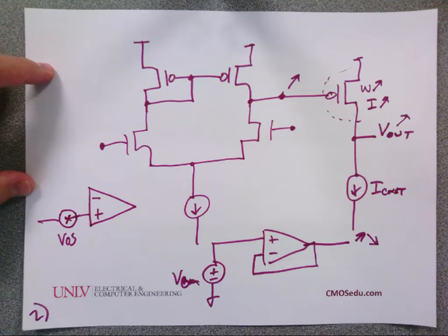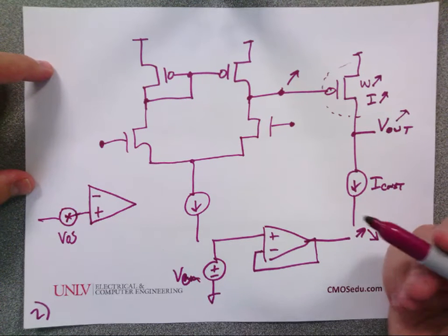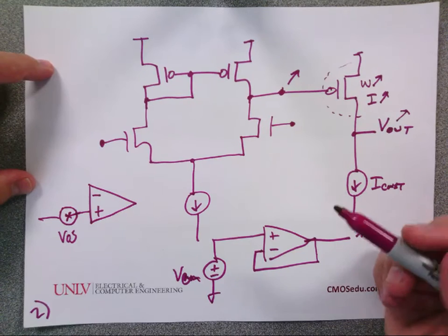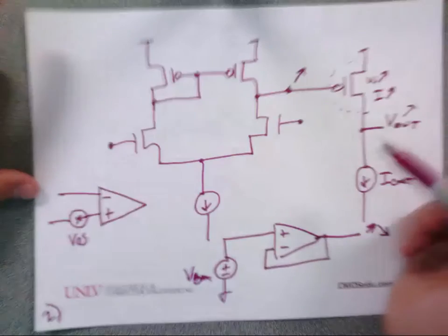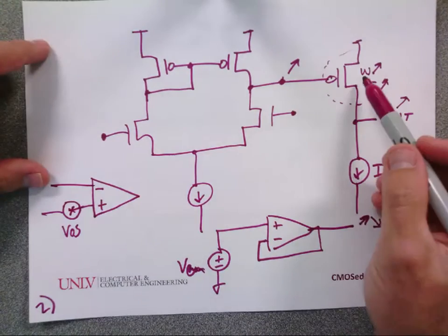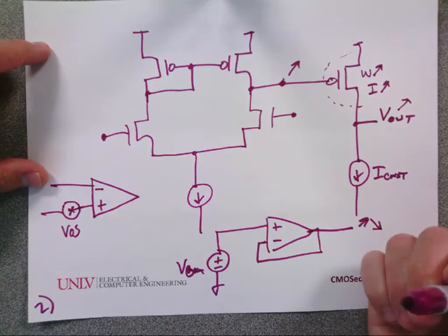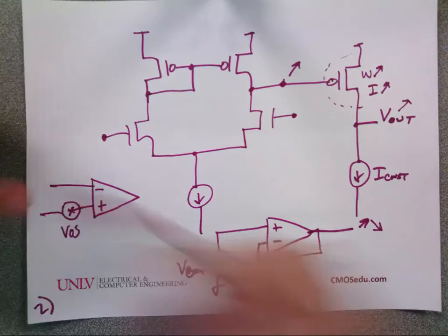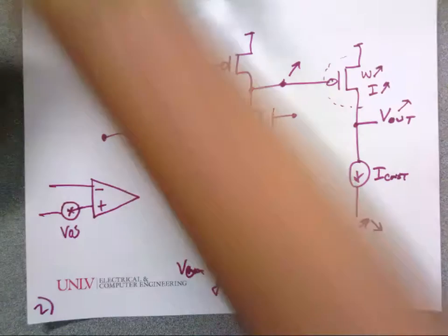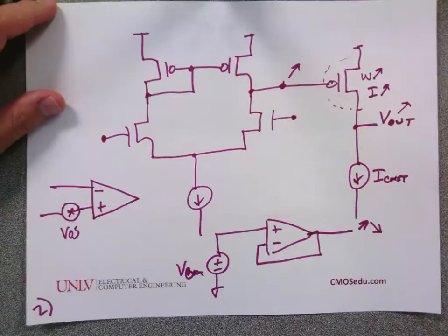Okay? Now I want to plot the transfer characteristics of the op-amp, then I want to talk about the slope and the gain. Okay, but does everybody see how if I don't size this right, I'm going to get an inherent or systematic offset? Okay, so I'm going to play around with this now.